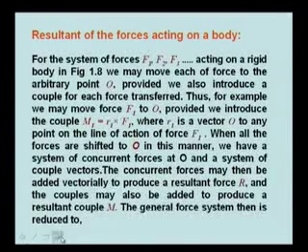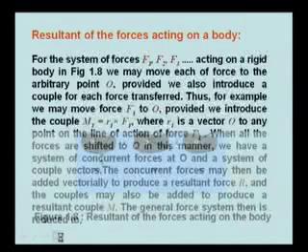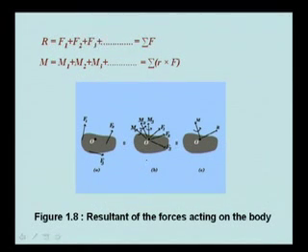Now, here suppose we move force F1 to that position O, then we also have to introduce a couple for that, because suppose this is a force P, this force acting here. Now, what I am doing is that this can be transferred to this point. How? I apply two equal and opposite forces at this point.